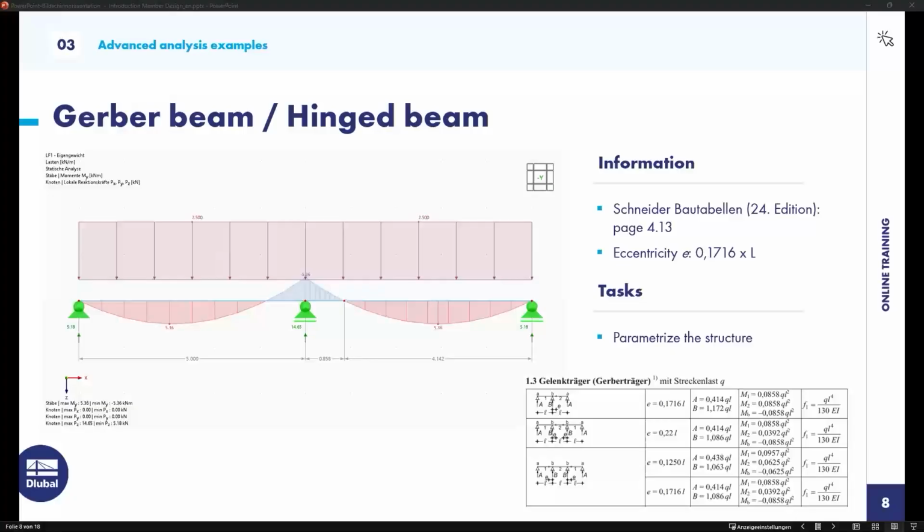And if you place that connection at the spot where the bending moment is 0, then you can simplify that connection by far. So this is a clever way of splitting beams in a good way, let's say.